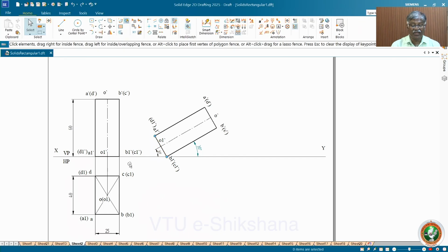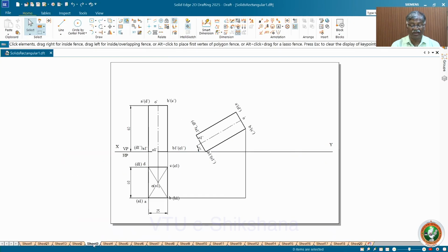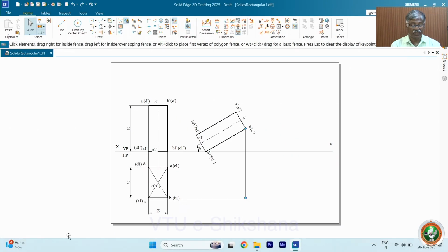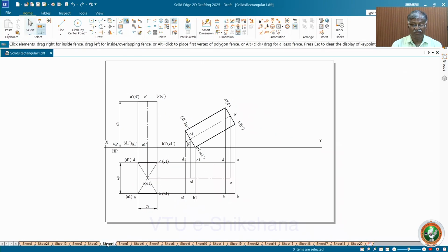Now after getting this, you try to draw the projections towards the second figure top view, complete the second figure top view with thin lines. For that you must keep this manually, do it, and even on the computer, we have to use the alignment indicator and do it. Here we worked out and got the points. Assume that we have taken all the points into consideration, base corners and the top corners, and keep it ready with light lines. Then the visibility concept.